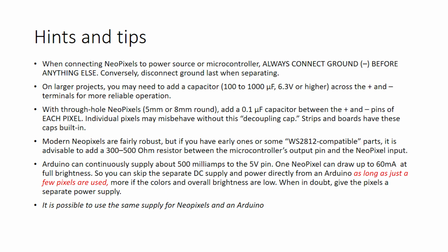Another thing to think about is if I've got, as I say, 15 of these as an amp, and because of the nature of how they work, they go from being in a certain position to being in another position. They all turn on, they all turn off, some turn on, some turn off. So the current that is being drawn from the supply is stepping up and stepping down and stepping up and stepping down. Not every supply likes that. Battery supplies don't like stepped draw like that. They sometimes get a bit warm if you do that.